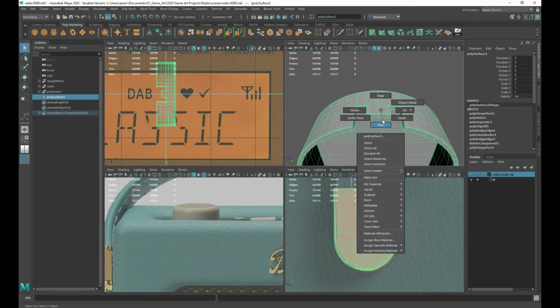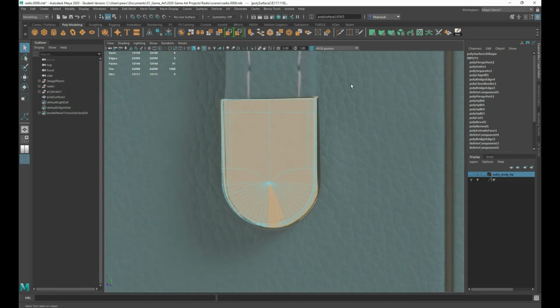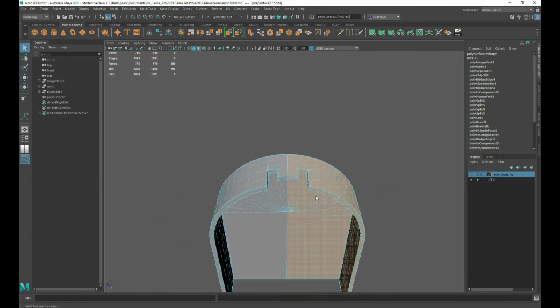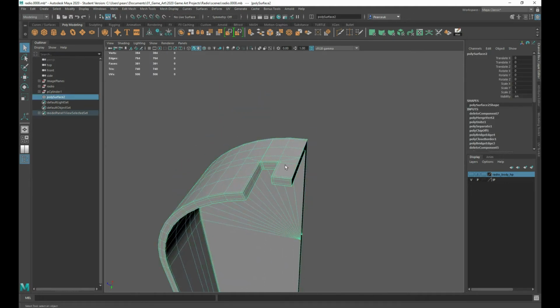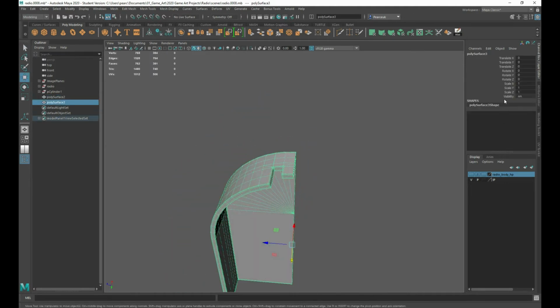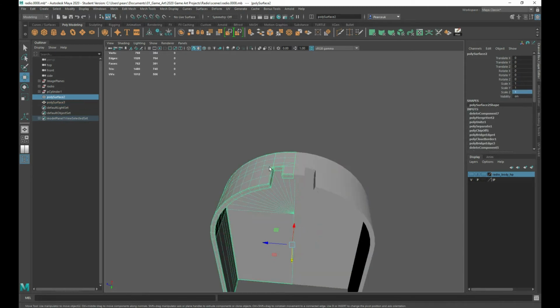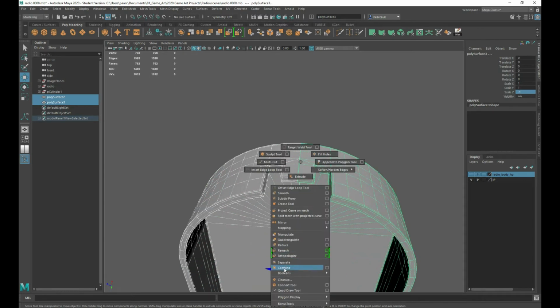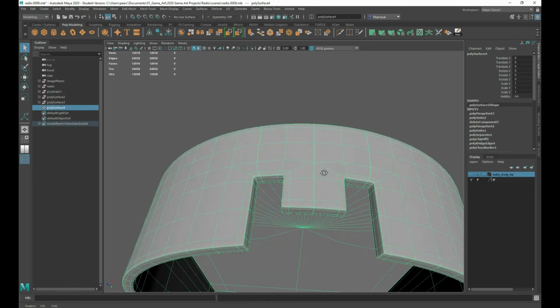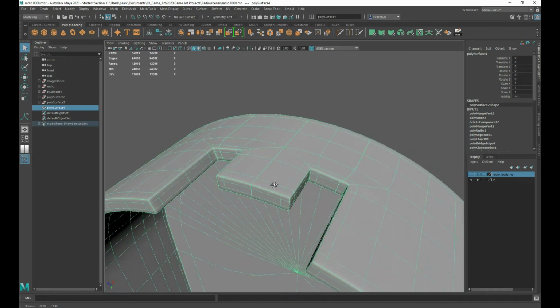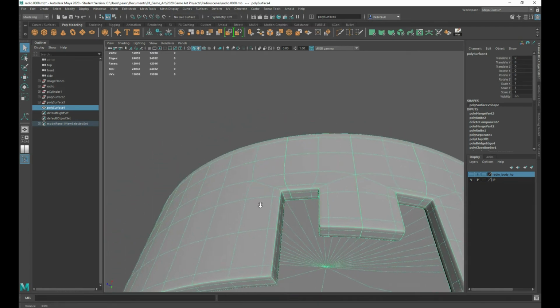And then now I can take this half completely and delete. Weird, very strange, but rather than trying to figure out and fix it, I'm just going to duplicate and mirror it. -1. Normally I get one dodgy side, but to get both is a bit strange. And then combine, vertices, all, merge. 3, and now it's kind of looking like I would potentially expect it to look.